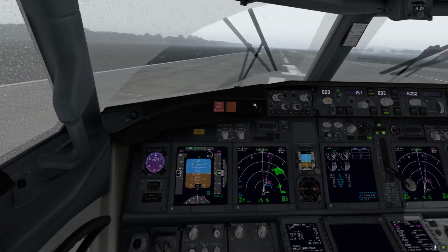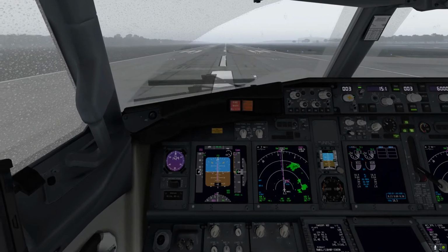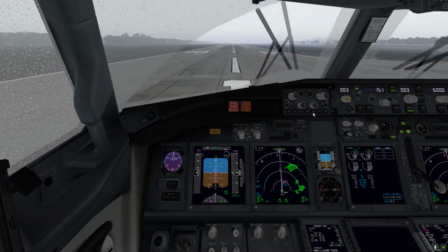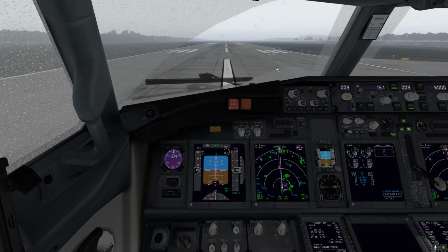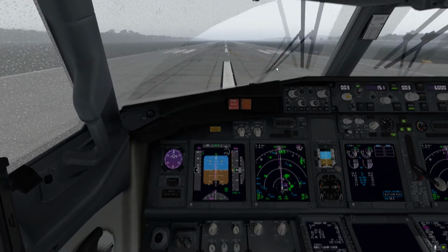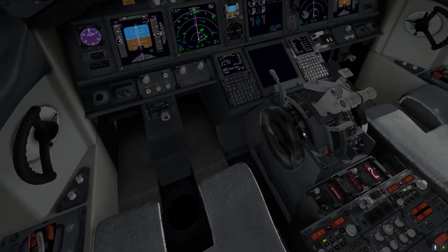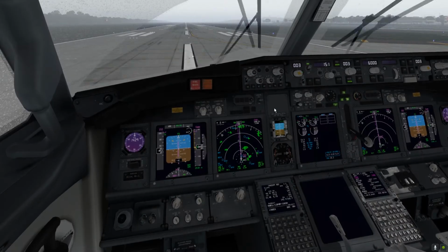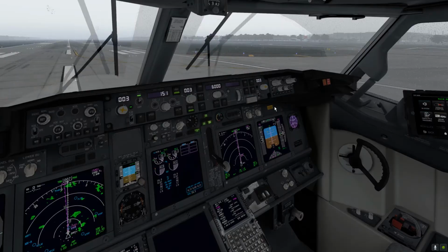Very important to have a look with the weather radar about what's going on up here or around the airport. Not really big activity of CBs, but some of them are present. So yeah, let's go with the before takeoff checklist. Flaps 1 planned, 1 green light, stabilizer trim 5.75 units set, and cabin call is given. Before takeoff checklist is completed. Off we go.